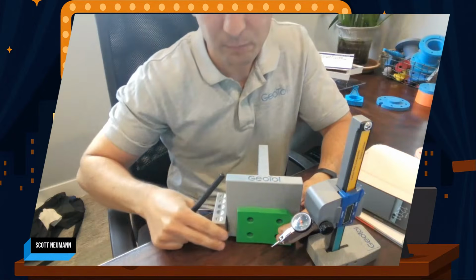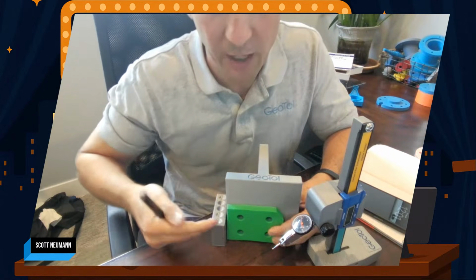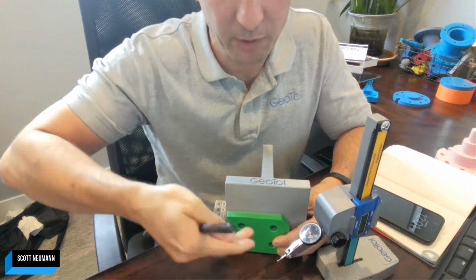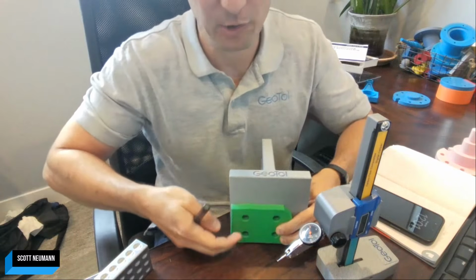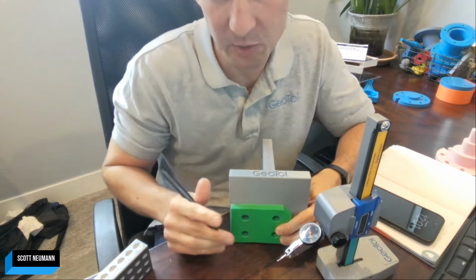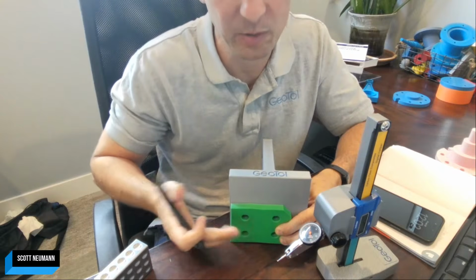Oh, you wouldn't need a CMM for something like this. This is such a simple geometry. This would be very easy, an angle plate with a basic height gauge. So you'd set up the angle plate, set up A, set up B. You'd have probably a gauge block over here for setting up your C, and then measure the hole in the Y direction, rotate, measure in the X direction, and then make sure that combination of X, Y, like Costas was saying earlier with the Pythagorean theorem, still lies within that tolerance zone.